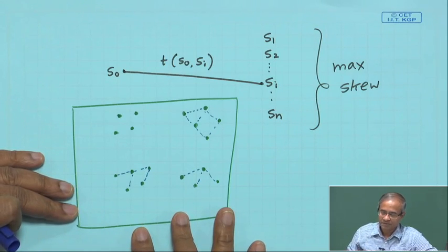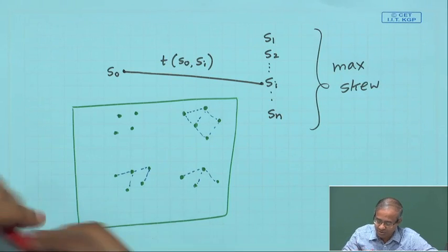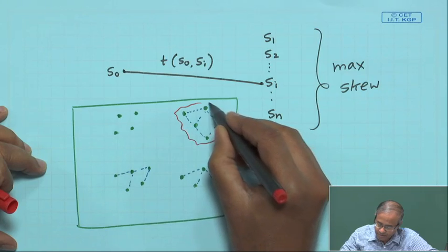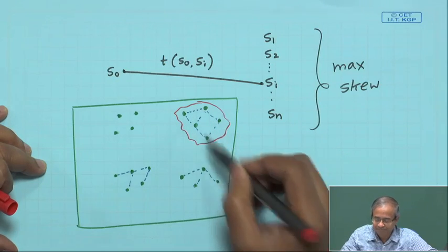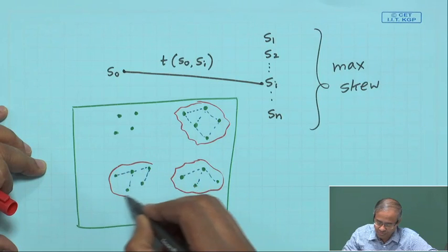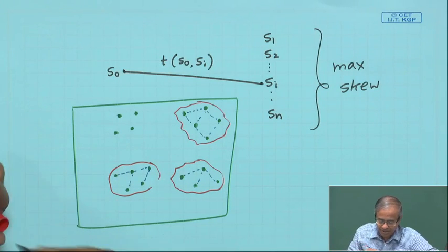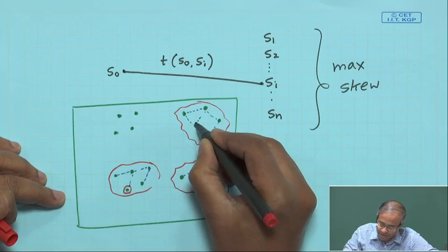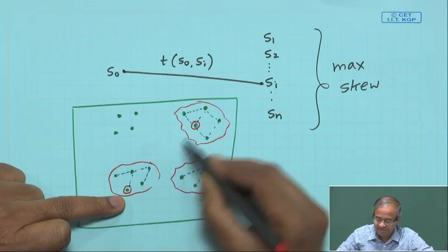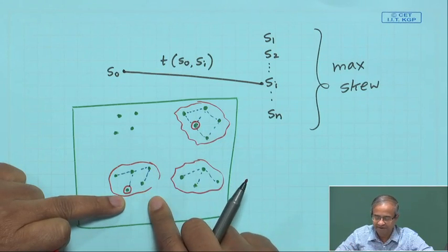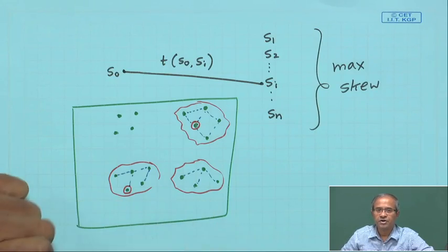So, what I mean to say is that for correct operation, we must ensure that in every zone the flip flops which depend on each other should not have too much skew among themselves. Similarly, in this zone or this zone, this skew has to be limited. But if you take a point here and a point here, they correspond to two storage elements, but they are not directly connected. So, even if there is a considerable skew between these 2 points, that will not affect your circuit operation. So, although theoretically skew seems to be a bad thing, all skews may not be equally important.